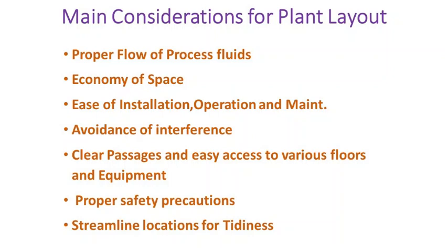And layout should start with the detailed project report itself, where we try to focus on the topography and geographical conditions, and we have to see the major resources, connectivity of power and roadways, and load conditions, and how generated power can be distributed to the national grid.